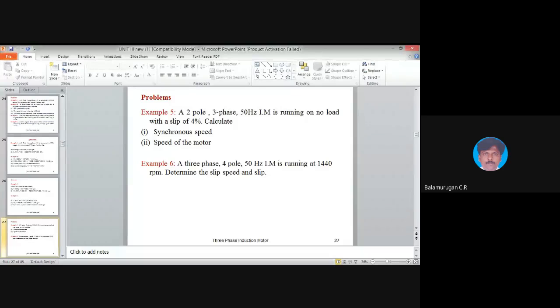As per this only, the three-phase waveform will be generated like this. It will have some magnitude, and here we have the time period. This is for R phase, Y phase, and B phase, and we have the angle as 180, 360. Each and every phase will have a time lag of 120 degrees, a phase displacement of 120 degrees. So this is the nature of the waveform.